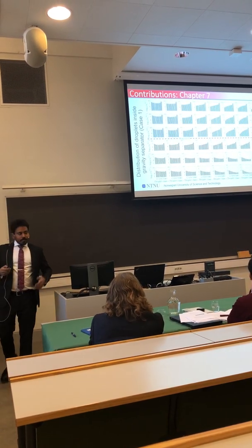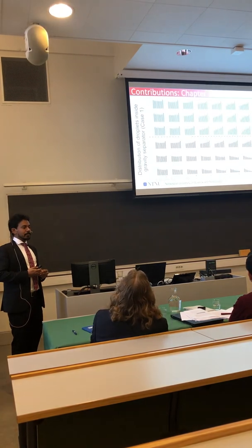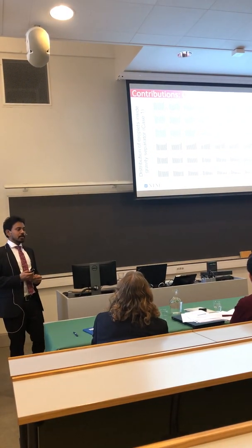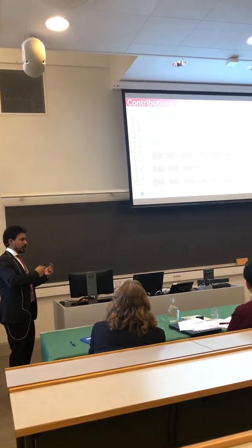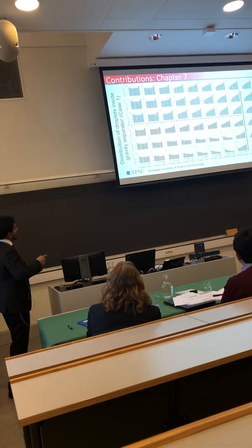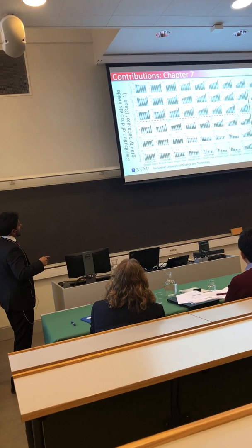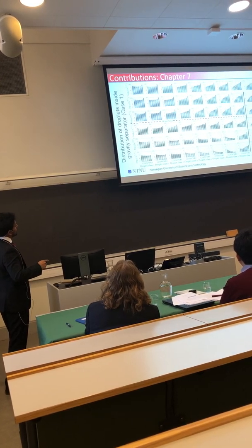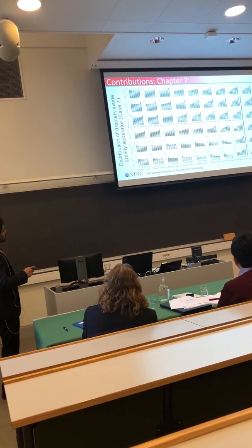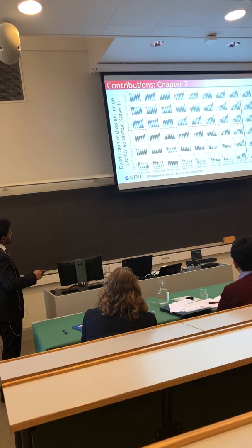The result of the coalescence is that we can estimate the concentration of oil droplets as well as concentration of water droplets in the oil layers in the different control volumes, and the oil droplets in the water layer. And here we see that as we go, this is the water level and this is the weir height. And as we go to the right, we see that these numbers are going down clearly because there is some non-convective transfer. The same happens in the oil layer where the water concentration is reducing.